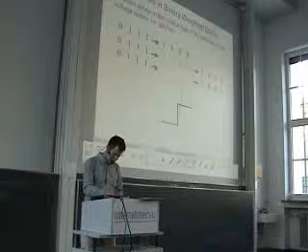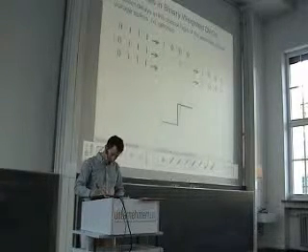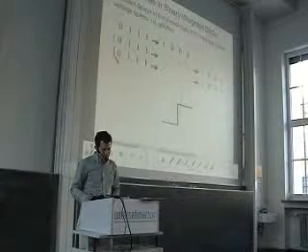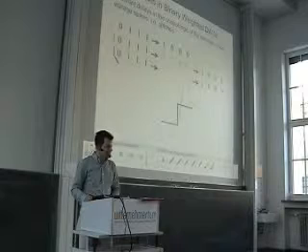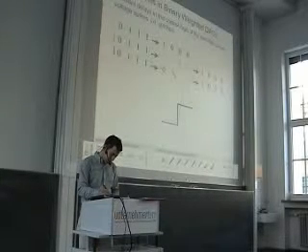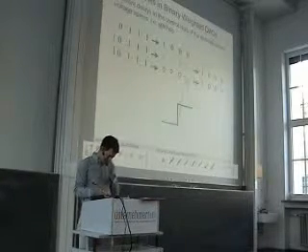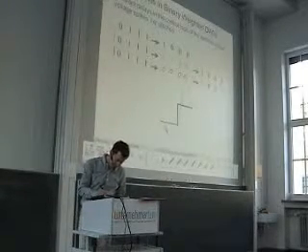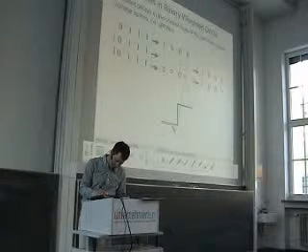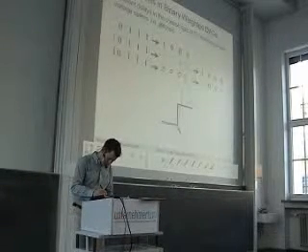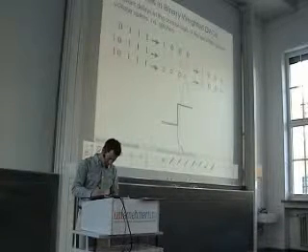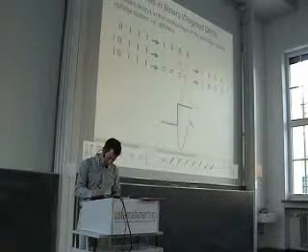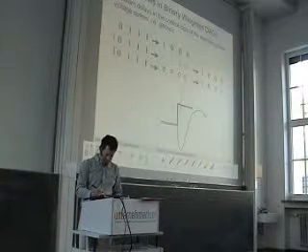Or in another situation, the MSB might be too slow. Then we may have an intermediate situation where all bits are 0. And then my signal looks like this. I go down, then the MSB switches, and then I go up again.